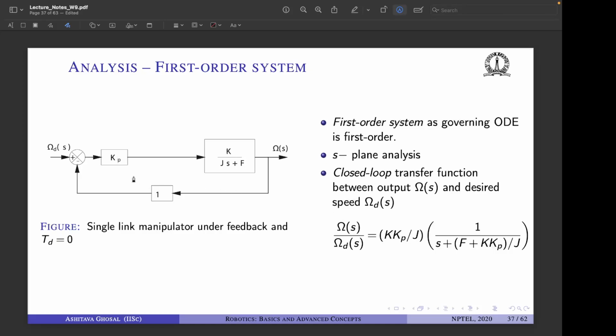So this is the closed loop. As we saw, this is the closed loop with a simple control scheme of Kp times the error, right? And this is something that sets up neatly for analysis. So till now what we have established is that a closed loop control scheme provides robustness from change in internal parameters, and also robustness from external disturbances. And this is the case where we are using a very simple closed loop control scheme, that is our applied voltage is Kp times the error between the actual velocity and the desired angular velocity.